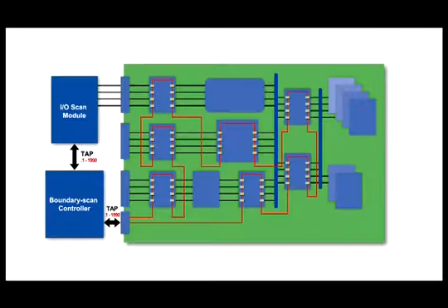Unlike a bus measurement, which tests one connection at a time, an interconnect test tests all connections between boundary scan devices simultaneously. By combining external boundary scan devices, also off-board connections can be included in this test. An interconnect test can be generated automatically and is generally used in production.